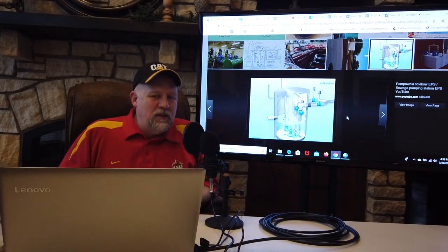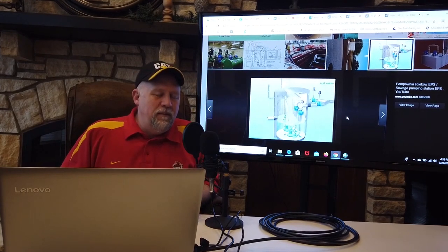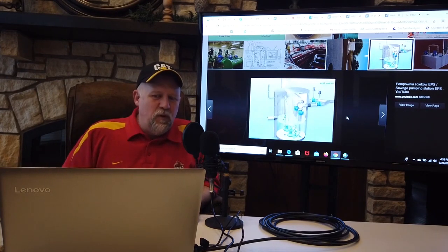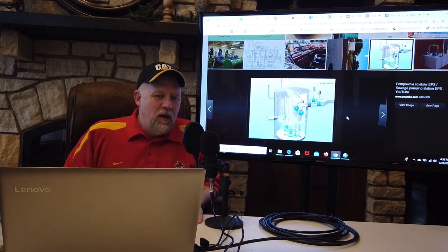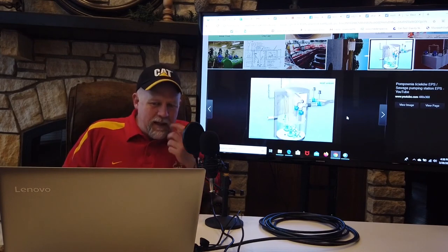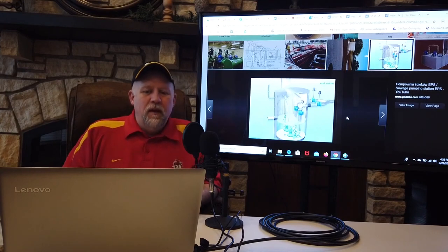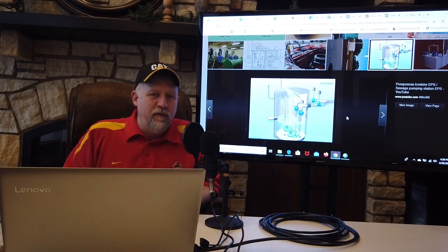You might see lift stations on properties, but you also might see large lift stations across cities. It would make sense, right? Because we can't just keep going as the city gets bigger and bigger. It's not possible to only build on higher and higher elevations so everything flows to the sanitary sewer treatment facility. So periodically within a system or within a city, you're going to have a lift station that takes that sewage and lifts it up so that it can continue in a gravity drain type of format.